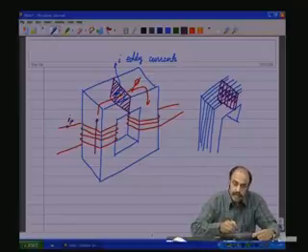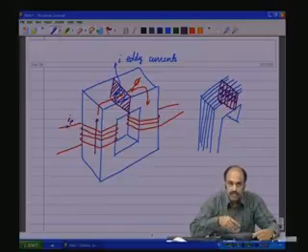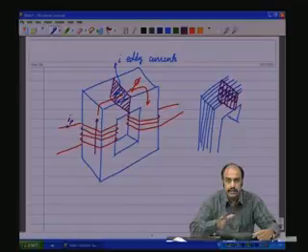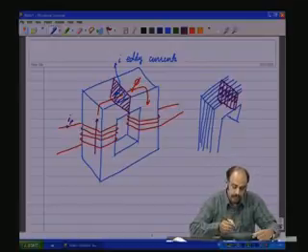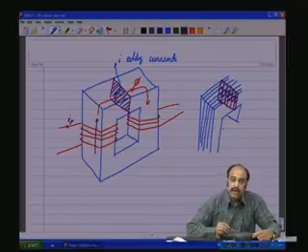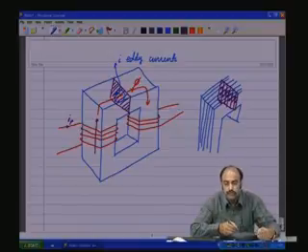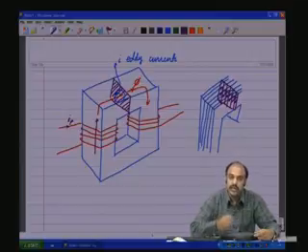So, this way the eddy current losses can be reduced, and that is why in power transformers you will see that the core is laminated and not one solid piece. Otherwise, if the core is made up of a highly resistive material like ferrite, then the use of laminations is not warranted. One need not use a laminated core. They could use one solid piece of core material because the resistivity of the core material itself is high, which will reduce the eddy current losses.